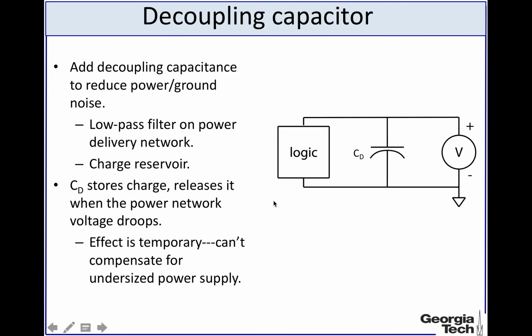So how do we nullify the effect of such resistance occurring either in the source or the drain? Usually ground bounce happens when a lot of the gates in a logic block are active at the same time, meaning that they're switching at the same time, and a lot of current starts flowing in and out of this logic block through the source line and the ground line.